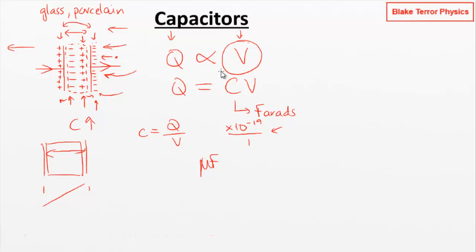Another difference with batteries is that capacitors might not have the energy density, but they can discharge very, very quickly. You can have a problem with batteries if they discharge quickly, because it can end up damaging the structure of the battery. With capacitors, you don't get the same issue, or at least not to the same extent. So these electrons are ready to go. You can get a very quick, short duration input of energy on demand.